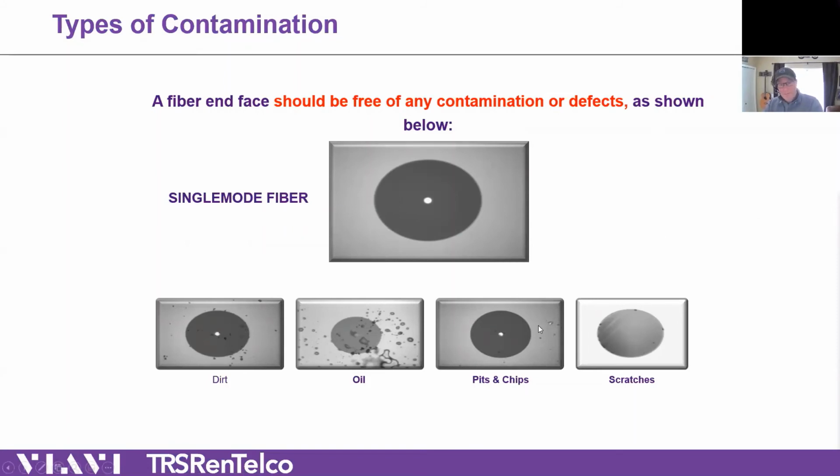Dirt's cleanable. Pits and chips and scratches are not cleanable. Eventually, you just cleave it and fusion splice an end on, or replace the jumper if you're dealing with short jumpers.